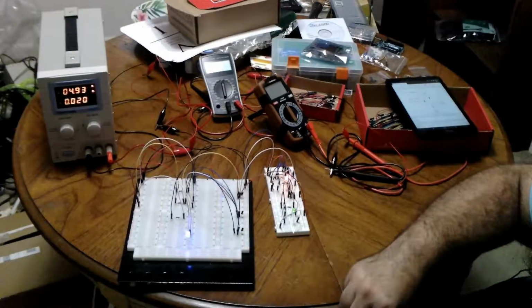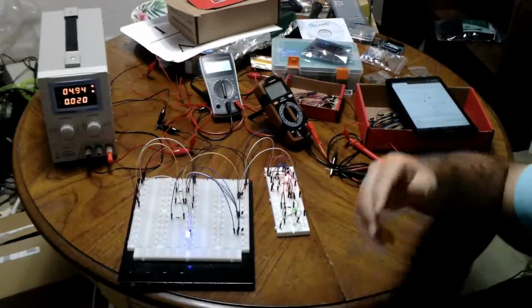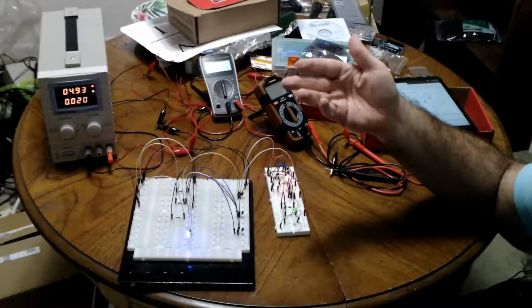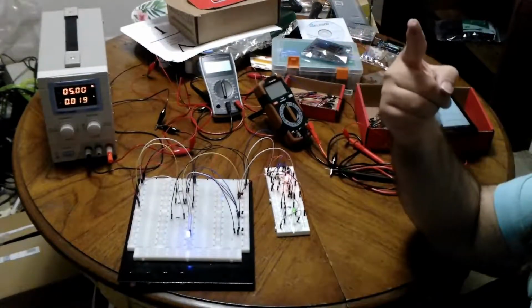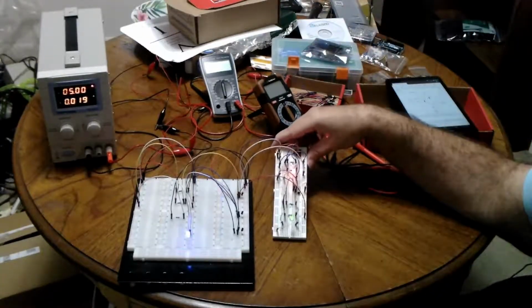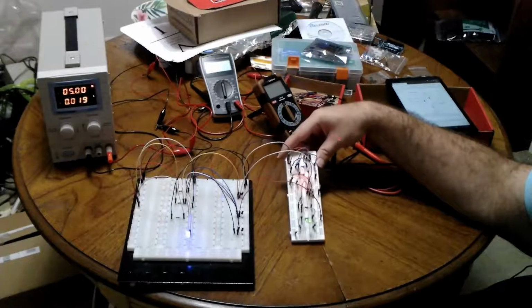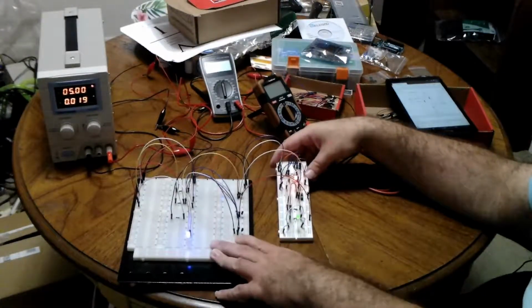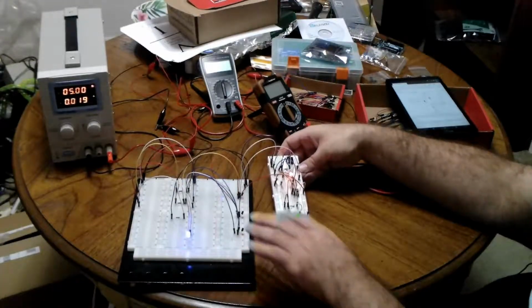That's our AND gate. It's a NAND and a NOT, because NAND is not AND. Not AND. Two negatives make a positive. And there's your AND gate. One more transistor, one more resistor, couple more wires. There you go. And you can see why I decided to have the input signaling circuit separate from the gate circuitry. I could even have had the NOT gate separate if I wanted, but there's enough space.